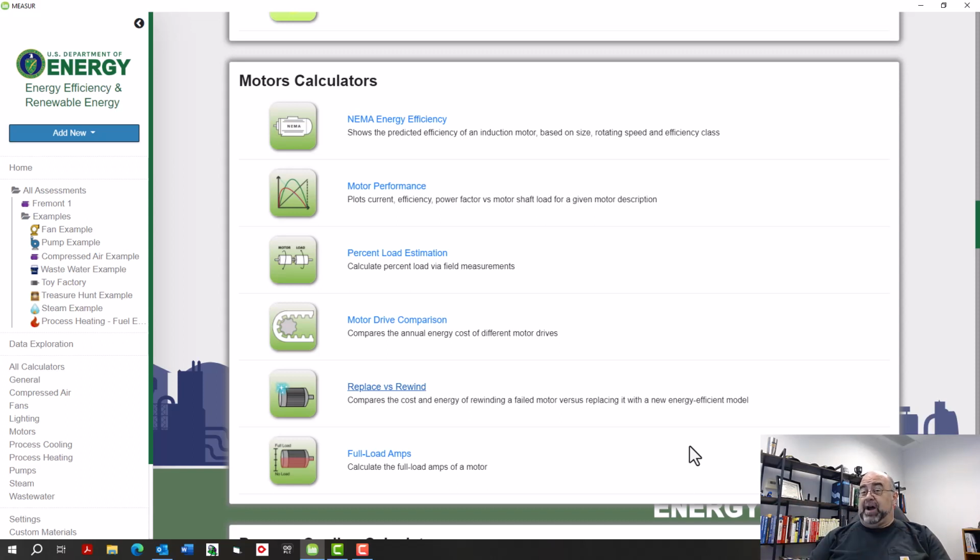Truly, it's supposed to be the motor power factor. And I've been watching some people's presentations lately, and they're equating system power factor as motor power factor. And look, all you have to do is this, and you can improve the motor efficiency. Absolutely false. Wrong, wrong, wrong. Those are two different types of power factor. The motor power factor reflects the calculated losses inside the machine, and the actual power factor of the machine, which cannot change unless I have damage to the machine, will affect its efficiency. But system power factor will not.